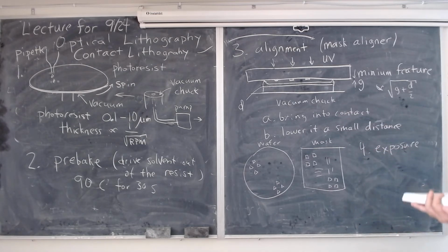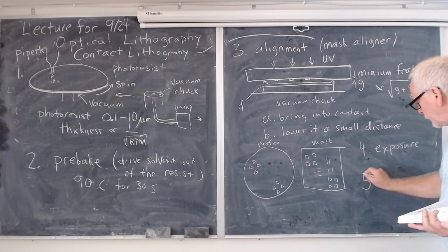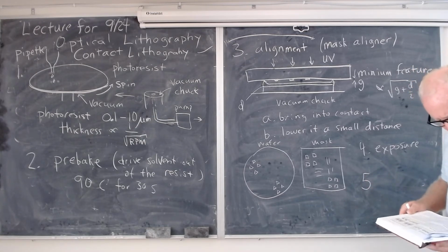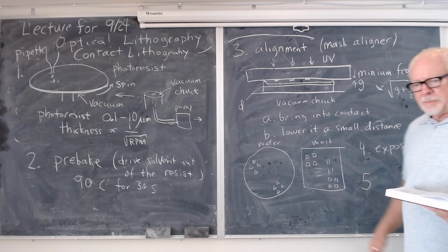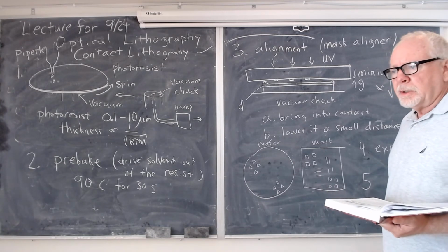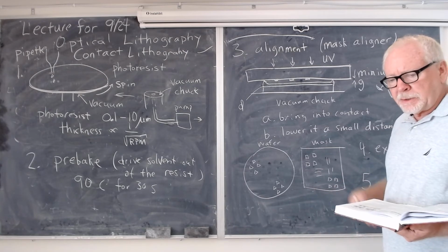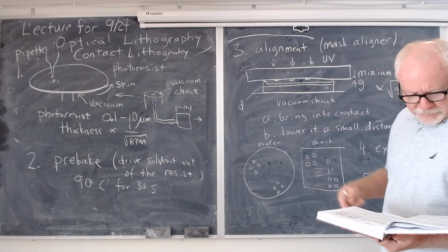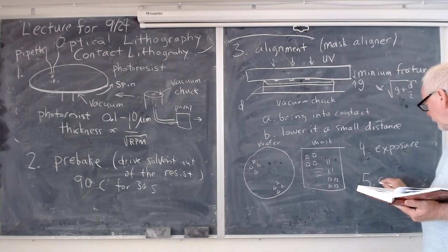So you do the exposure now, and then after the exposure, all right. Now here there are some people that like to do another bake after this, but it's not typical. Usually after exposure, you go straight to development, but I'm just saying as an aside that some people explore recipes where they put another heating step here, but typically it's in the developer,